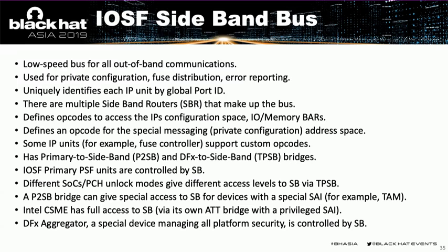The standard way to access IOSF sideband is via the primary to sideband bridge, but it's very limited. In fact, you can access only a limited number of devices and very limited registers. If a chip, SoC or PCH is currently unlocked by an Intel OEM engineer, you also have access to sideband via JTAG.